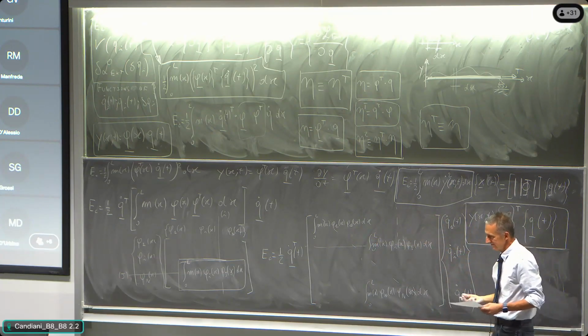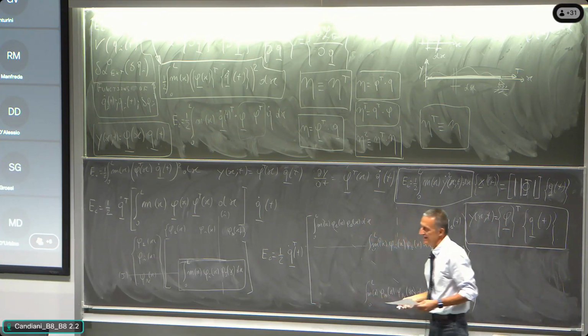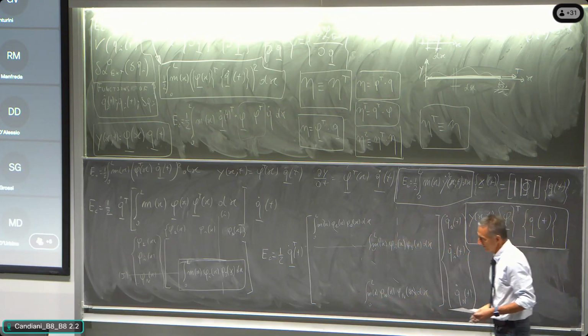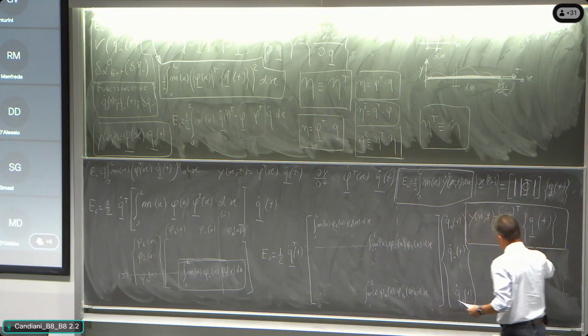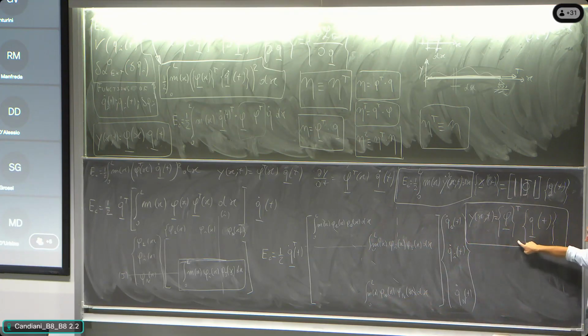But we are showing that for the elastic problem, the orthogonality property is that using the transformation in principal coordinates, that is this one, writing the movement of the system as the vector of the modal shapes transposed, multiplying the vector of the newly introduced principal coordinates.